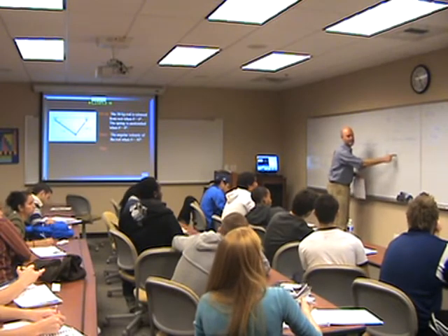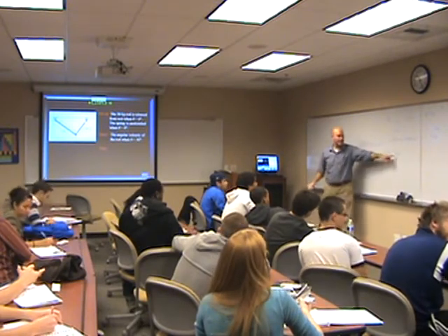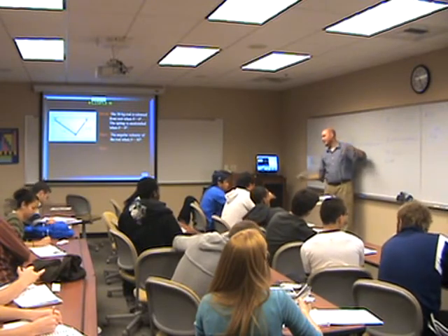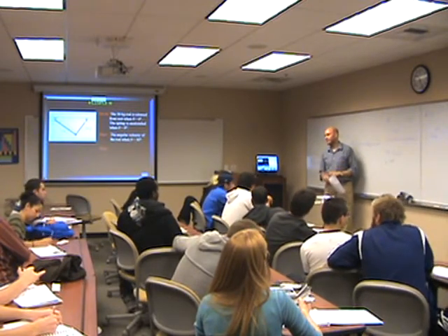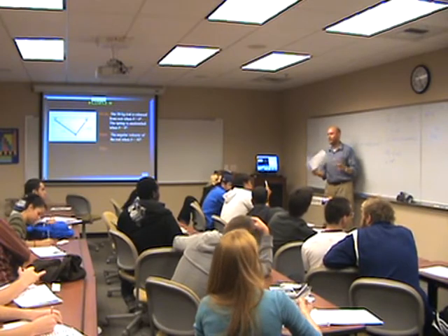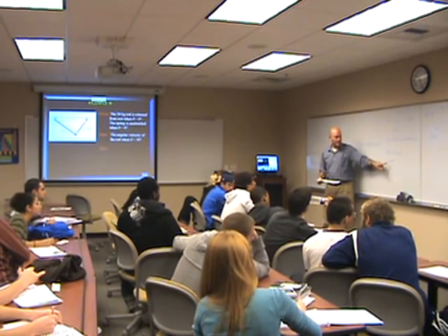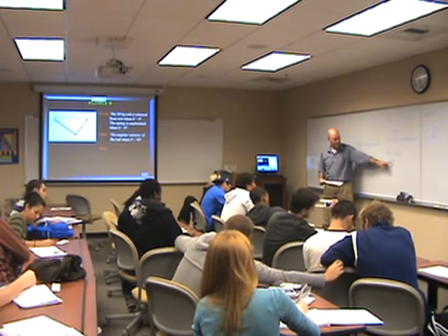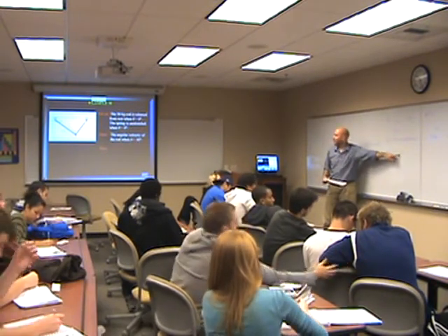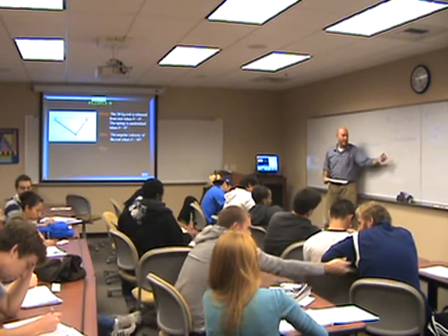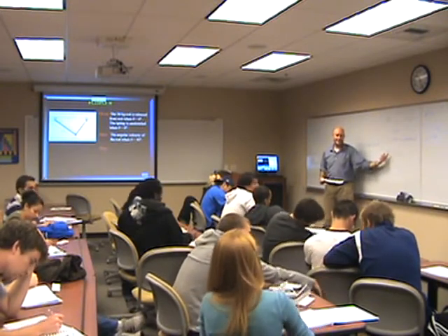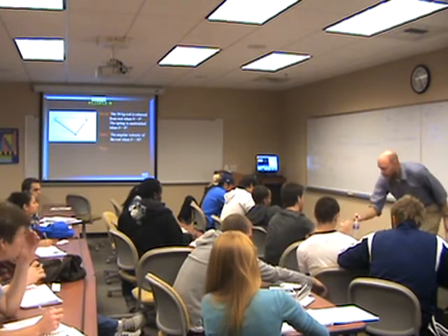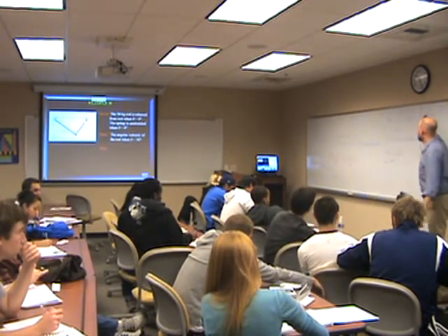So this is an advantage of using I_O, because I_O is actually in your table. It's 1/3 m L squared. If I_O is not in your table, then you might as well use 1/2 m v squared plus 1/2 I_G, both of which are in your table. But I_O is in the table as well, and that makes our life a little simpler. So when there's a fixed point, we don't need the 1/2 m v squared. Correct, you use the I about the fixed point.